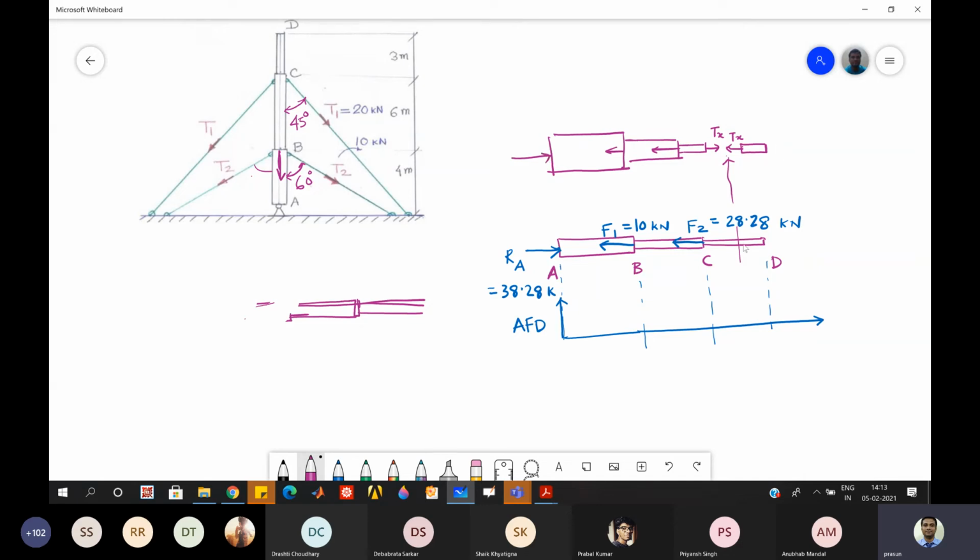Now if you see, it is easy to take this right side because there are no loads. And that gives us Tx equal to 0. The same thing we'll also obtain from this left side free body. So you have to choose the side which you feel convenient. Either one is fine. Technically, they're no different. So that means any section, if you take any point in this particular section, it will say that the axial force is 0. Okay, so that means it is on this line.